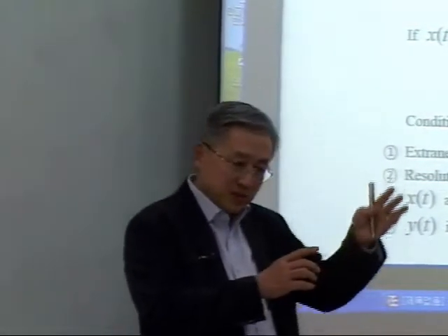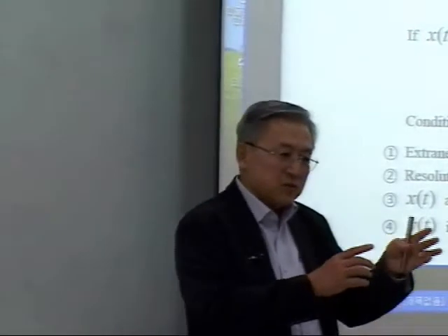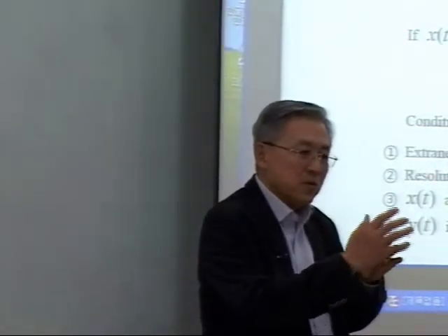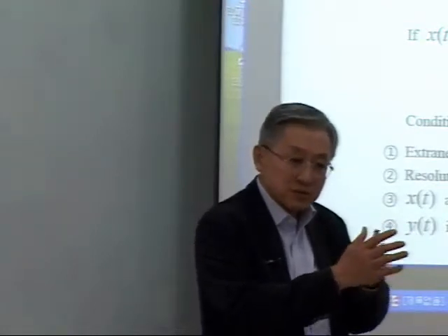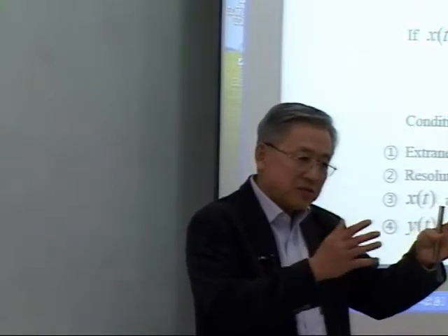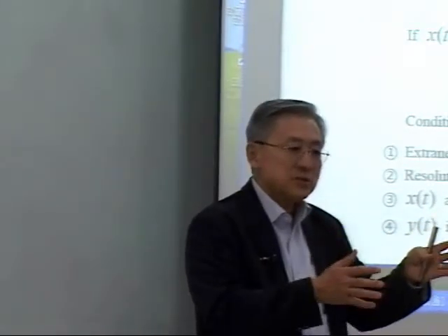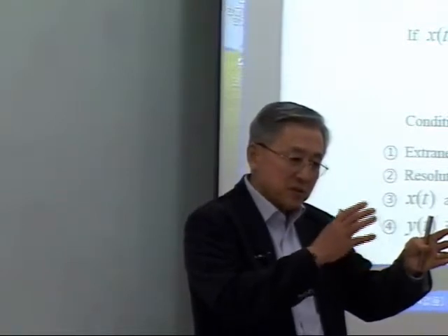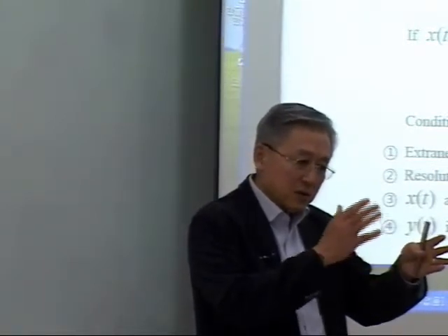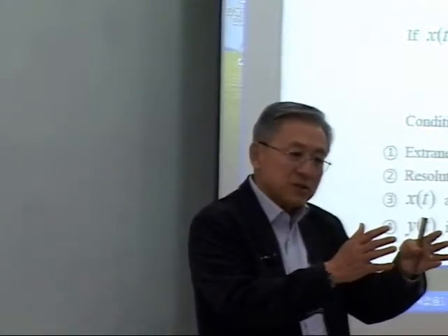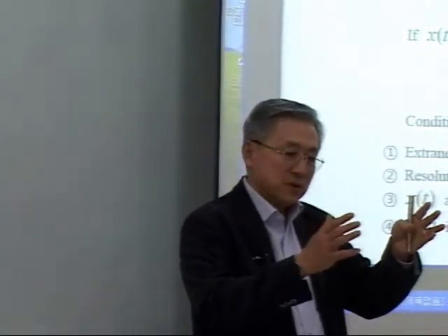In other words, the excitation frequency is approaching the first fundamental frequency, right? When it sweeps, then right at the resonance, when the excitation frequency hits the fundamental or lowest frequency of the plate, suddenly resonance occurs.